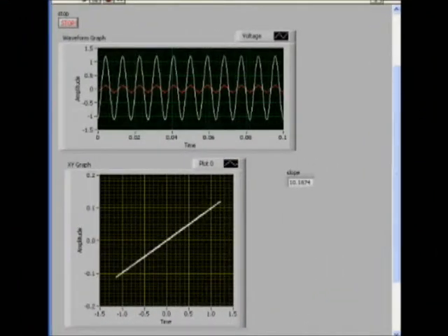So here we have our output graphs from our DAC readings of the voltages across our R1 and R2. As you can see from the graphs, this is a non-inverting op-amp setup because both graphs peak at the same point and they are not set up opposite like they would be in an inverting circuit.